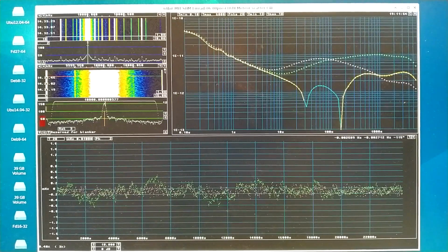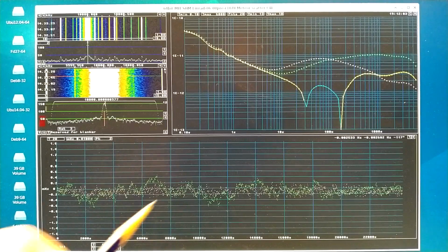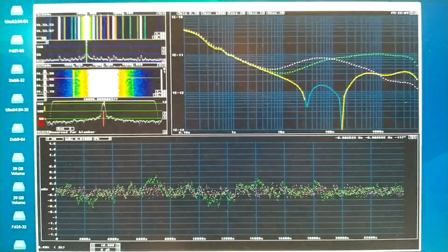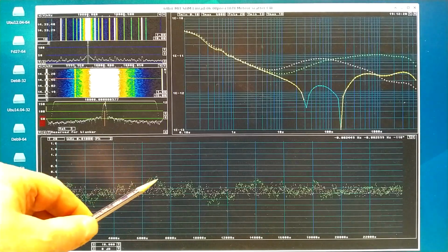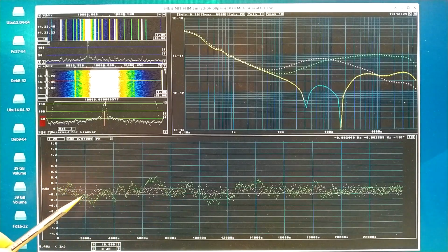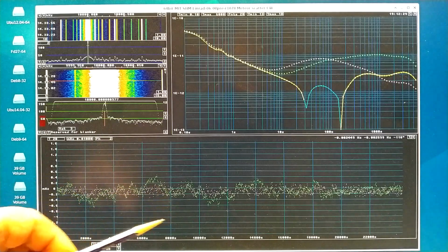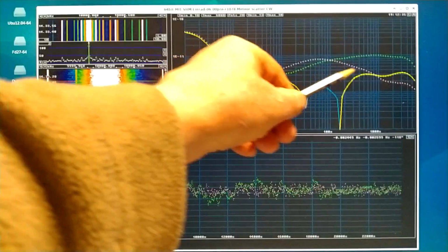I have been collecting Allan deviation for 19 hours now, and it seems I have a result up to about 20 seconds here. Then statistics on the correlation becomes too bad, and I don't want to wait for that. But I can see interesting things. The channel 1 oscillator is definitely problematic. It has some instability problem that should be possible to fix. And I can see channel 2, it seems reasonable.